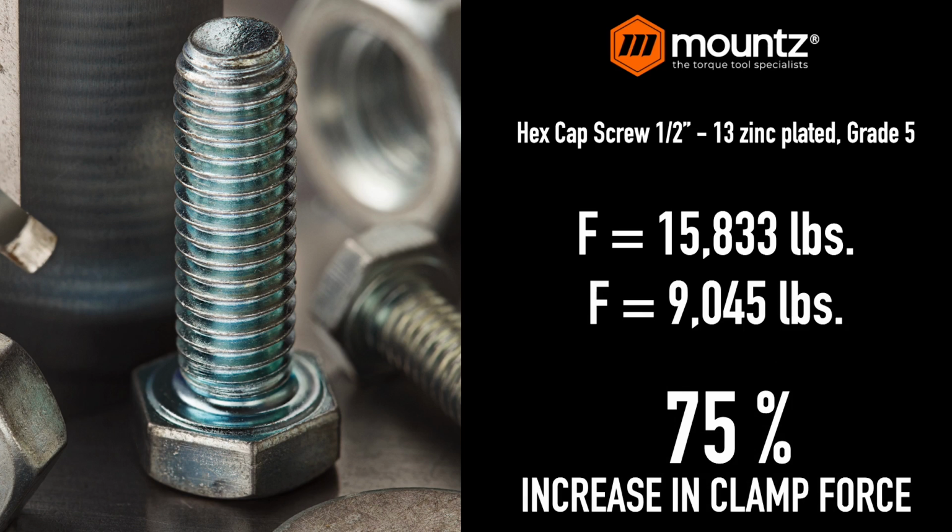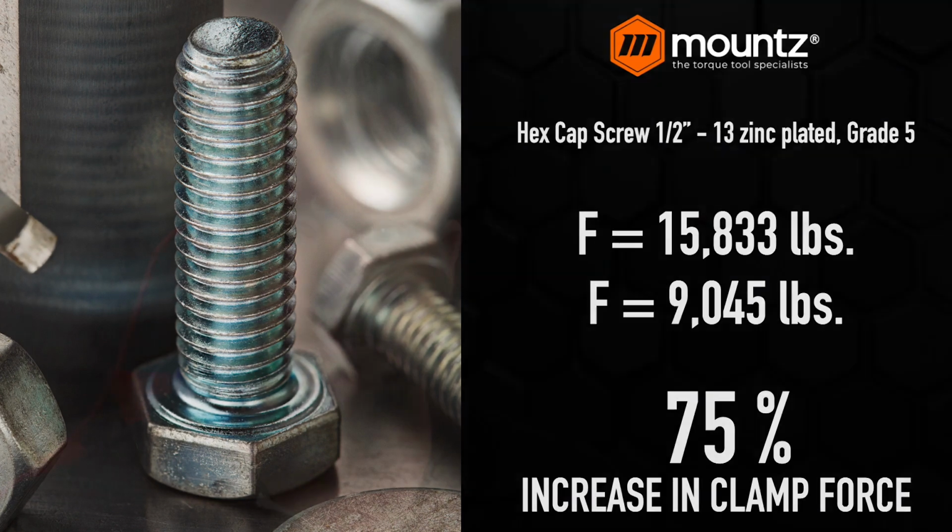And so this is where we can see issues with the fasteners getting into and past the proof load or the yield point for a particular application, all because one fastener is lubricated and the other fastener is not. So anytime there is a material change or any type of change in the application, it can really change the clamp force that we are dealing with for the output on that particular torque. So everything that we would use for the dry fastening, the torque was the same. We just used a different fastener.